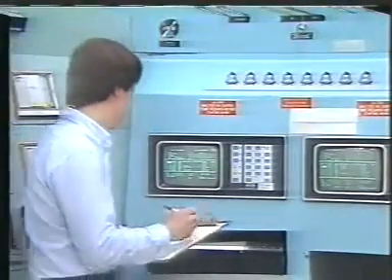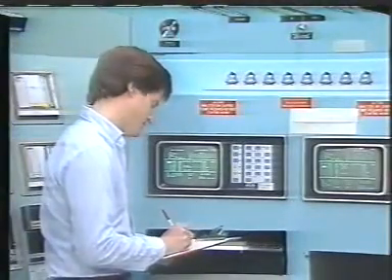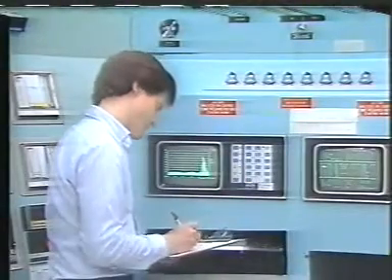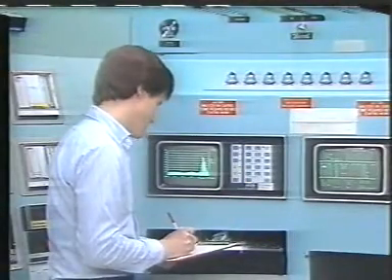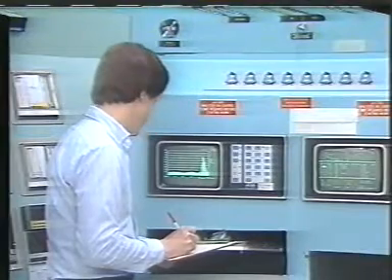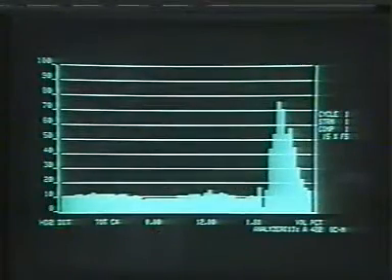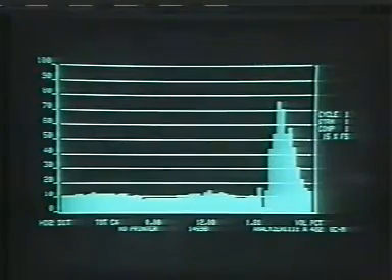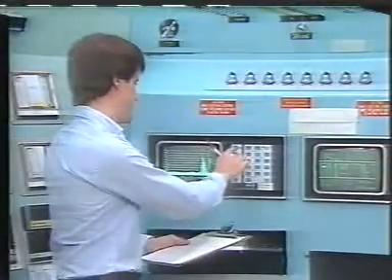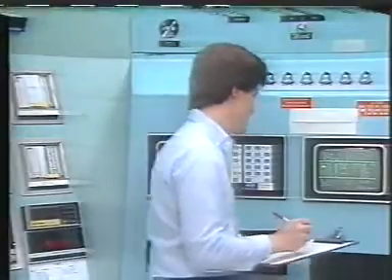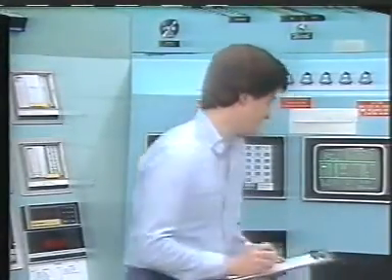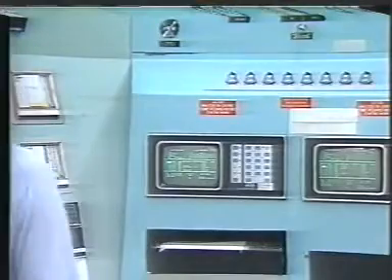Most computers rely on product composition analyzers to verify the accuracy of their predictions. The most common composition analyzer is the gas chromatograph. A gas chromatograph can analyze the composition of a product stream, just as the plant laboratory would, in as little as 30 seconds. This information is fed into the computer's memory to trim and adjust computer calculations and the output signals that are sent to control valves.